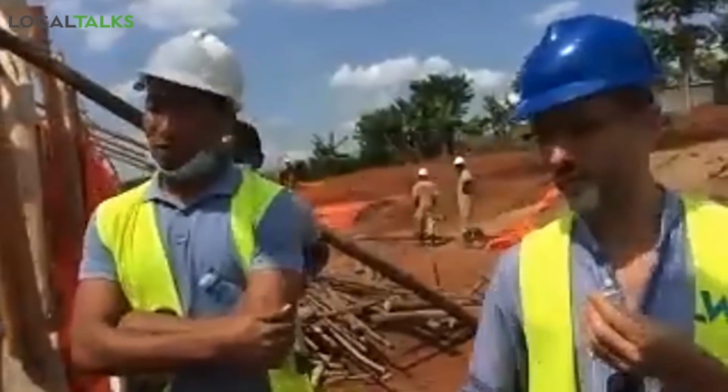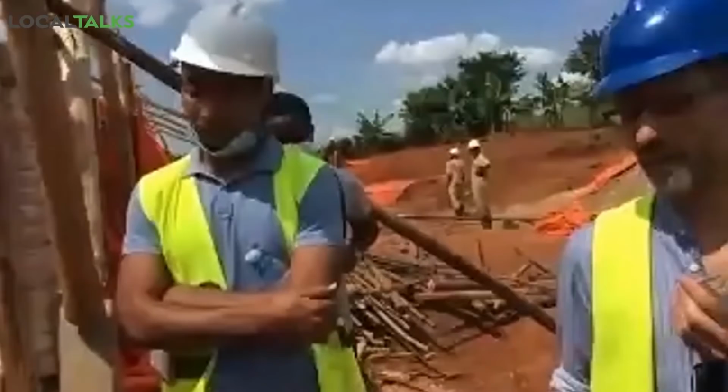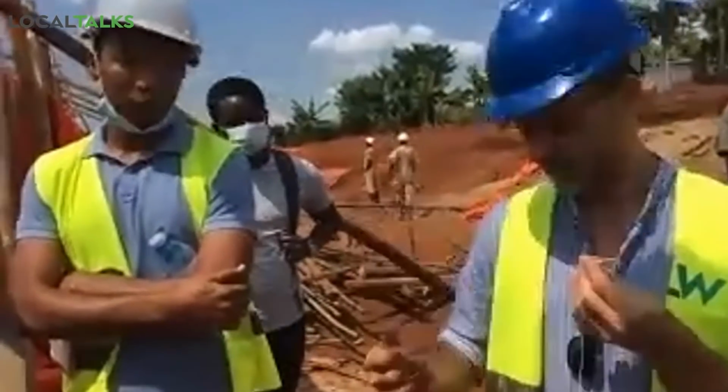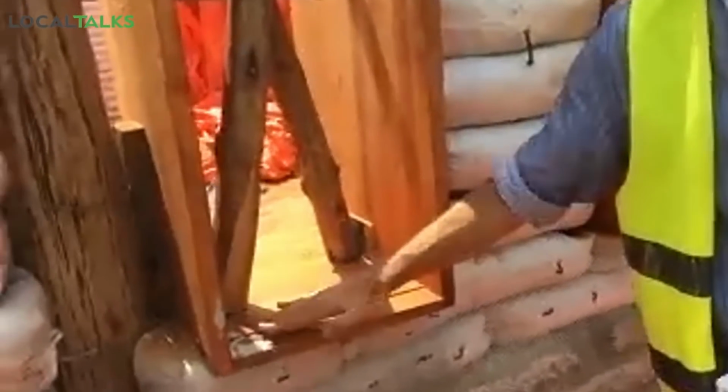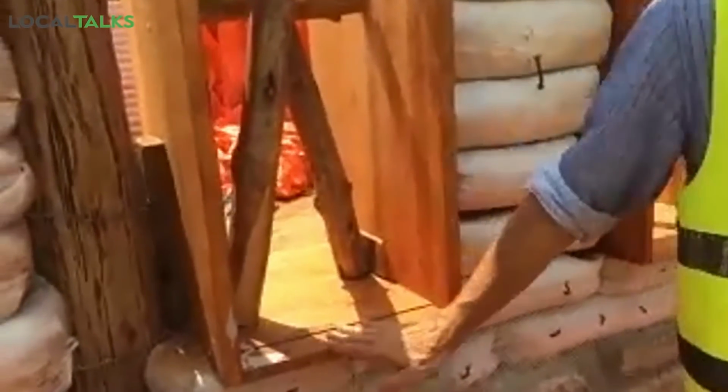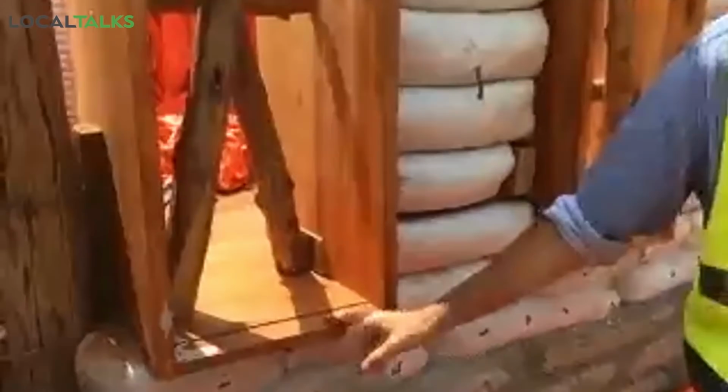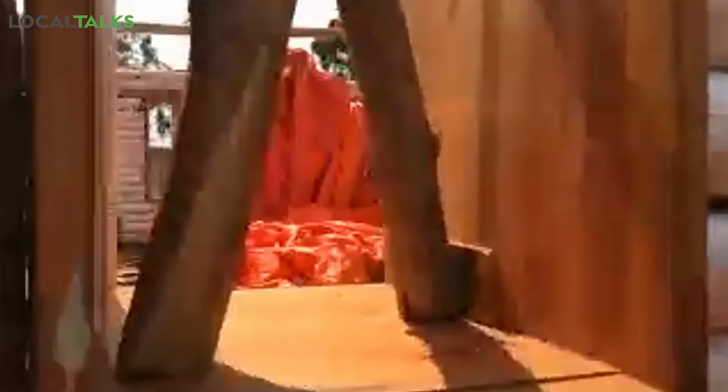The drip is there because in this particular case we will have glass louvered windows, and the lowest of the louvers will end exactly there, and we have a very small fall here, and we'll deal with water. That said, don't forget that we have a 2-meter roof overhang, and that we really do not expect a lot of water here. But that is the primary purpose of this. There's also a drip down here, so if there is any water in a controlled way.